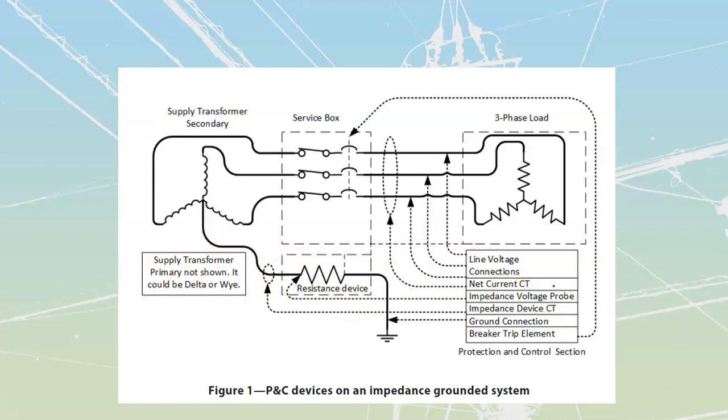Inside of a high voltage installation, you're going to have circuit breakers that are usually going to be battery powered. Let's draw in a little battery over here. That battery powered breaker is then going to have a little coil that is then going to operate the actual trip elements that we have over here. And so what we're going to do is monitor everything, and then everything that is monitored is going to send a signal back to our actual overcurrent trip.